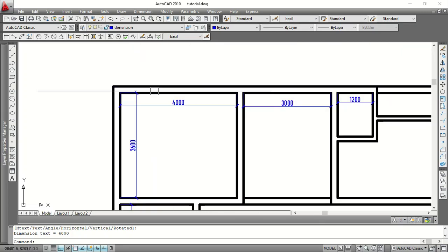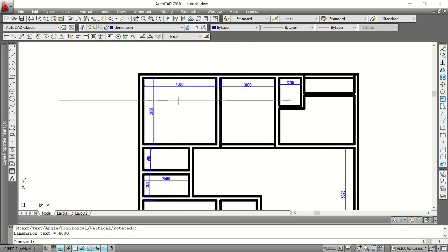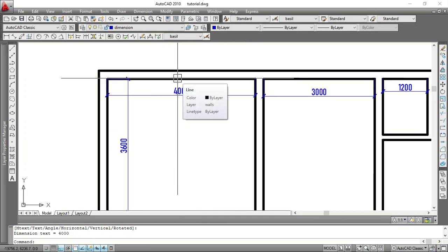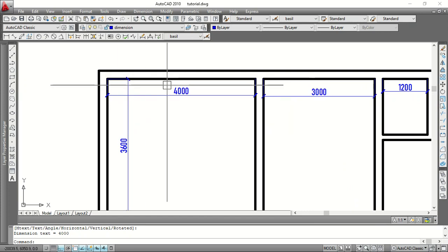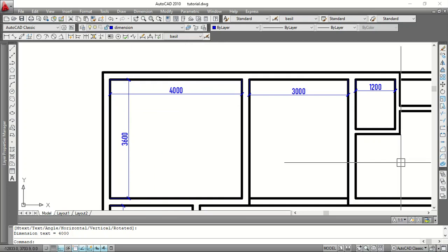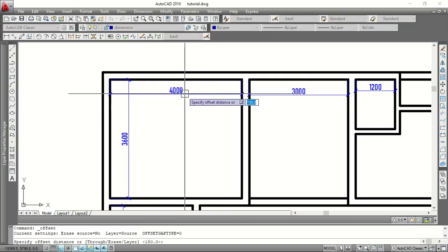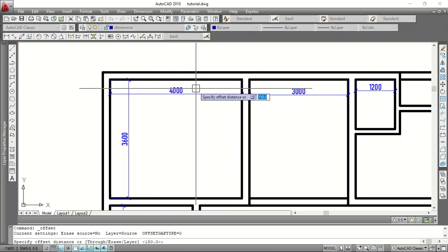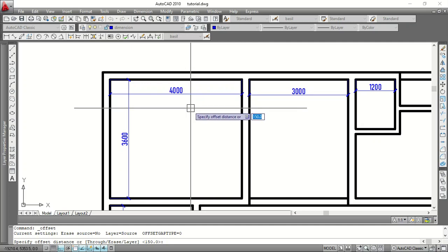All right, so I want to quickly establish my windows before coming to doors. All my windows, I want them centralized, especially for the rooms. The size of my windows is 1,200 mm, that's 1.2 meters. So I pick my offset. Don't forget, this is 4,000, so half of 4,000 is 2,000.